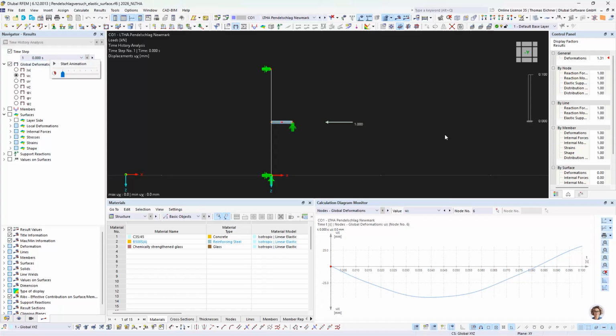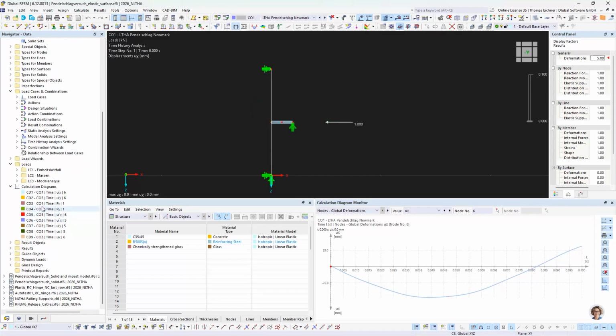Let's just start the animation. I will override it a bit so we can see more. Let's factor it with 5 and start the animation here. Now we see it's going to make the bang, and then it's going to rotate a bit. The thing with the linear one is that our spring non-linearities are neglected. That would mean it would still be connected in the end, and it would shift sinusoidally. It wouldn't be split after the impact. So this would just go up and then down again. For the velocity, maybe let's go for our time diagrams.